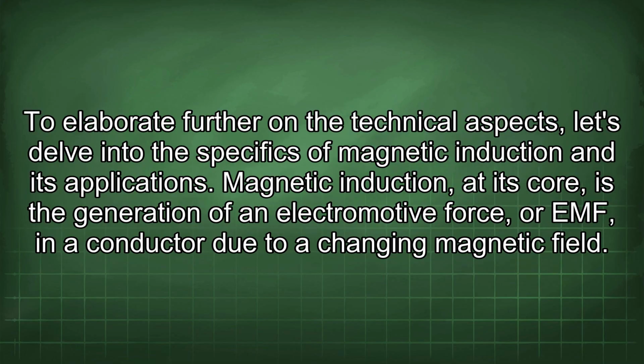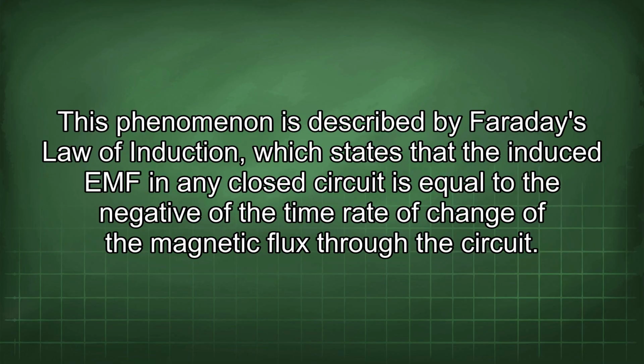To elaborate further on the technical aspects, let's delve into the specifics of magnetic induction and its applications. Magnetic induction, at its core, is the generation of an electromotive force, or EMF, in a conductor due to a changing magnetic field. This phenomenon is described by Faraday's law of induction, which states that the induced EMF in any closed circuit is equal to the negative of the time rate of change of the magnetic flux through the circuit.